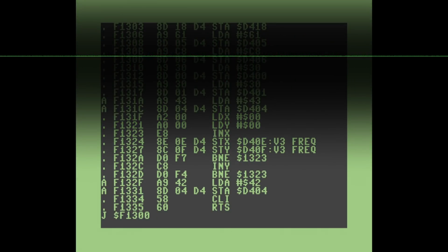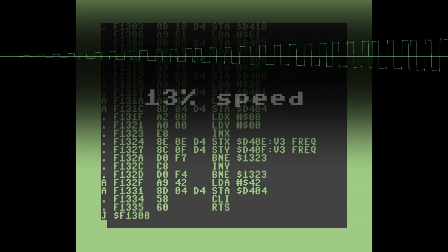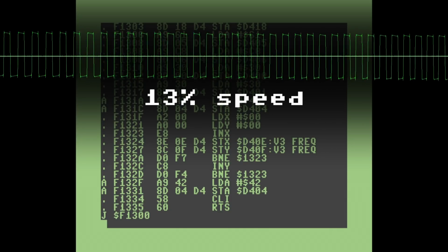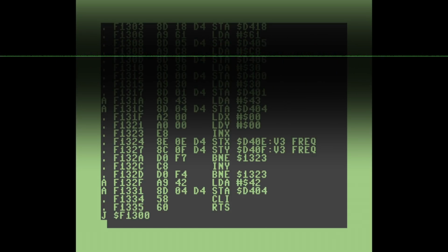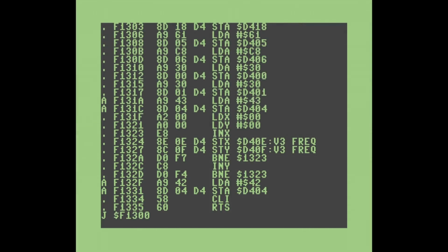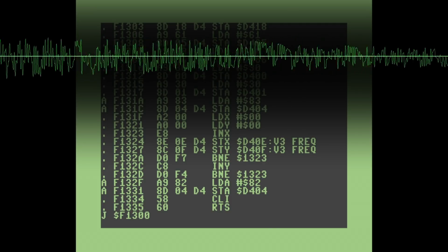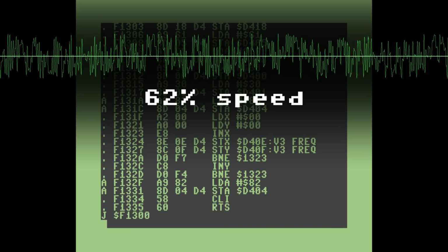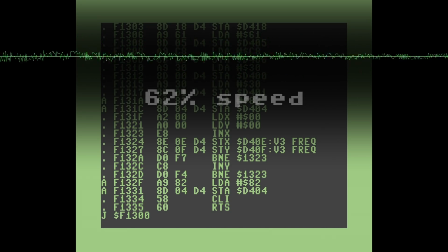In this case, the duty cycle of the square wave remains constant, but because the start of the wave is re-triggering at an increasing rate, eventually we end up with a constant amplitude and the sound seems to stop halfway through. Finally, let's see how re-triggering noise behaves. Since we're hearing white noise, re-triggering the wave causes a cycling effect in the noise. This can be used to good effect to create unique sound effects.